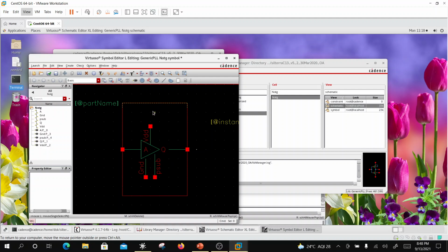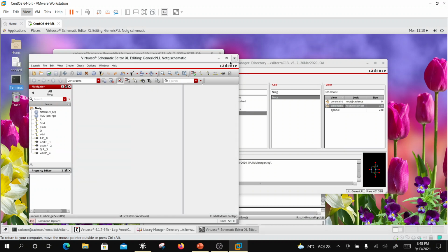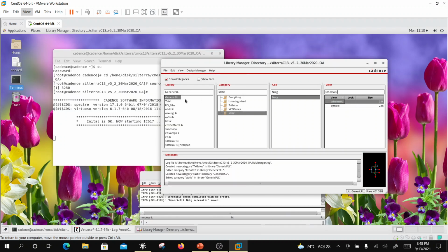Correct? And then I'm going to create a small bubble. The bubble goes here. That's the instance name. That's the path. Okay, and do a check and save. Done. And check and save and done. So we have the blocks, ready for the D latch.